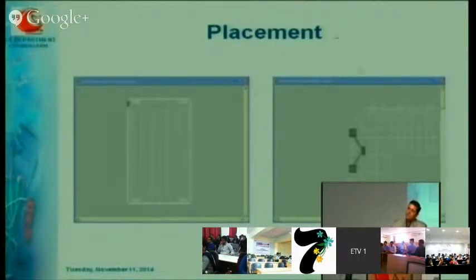Here you can see this is one block of IOs. Two pins are used here, two pins are used here. So for this one, this particular floor is selected, and once this floor is selected, then the part of that floor that will be used to place your circuit is selected, so that you get your placement and routing optimal.